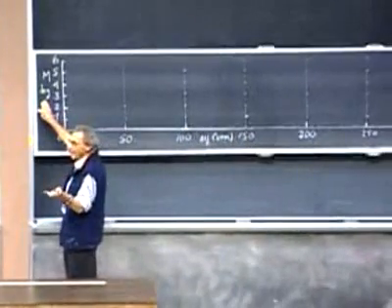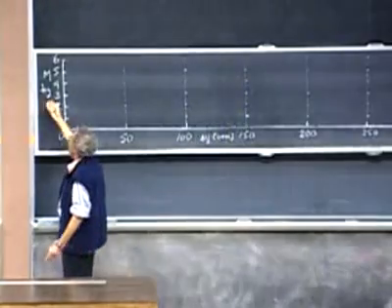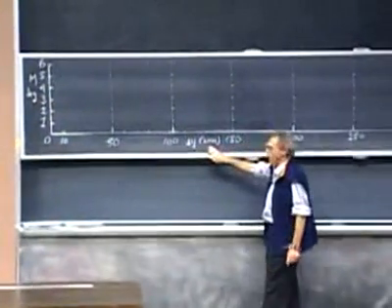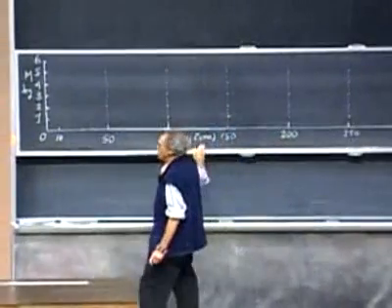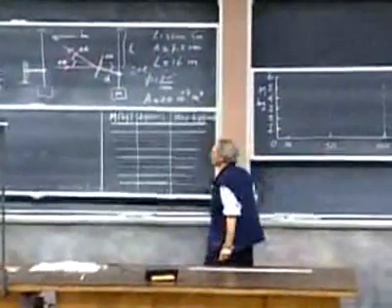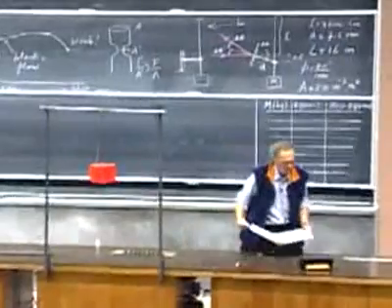to put here just the mass, how many kilograms we have on there, because we know what A is, so you can calculate F over A. That's not so important now. And here I simply have delta Y. But keep in mind that delta Y is always 425 times larger than delta L. And so we're going to plot it, and we're going to see whether we come up with a curve that is somewhat similar to that one.